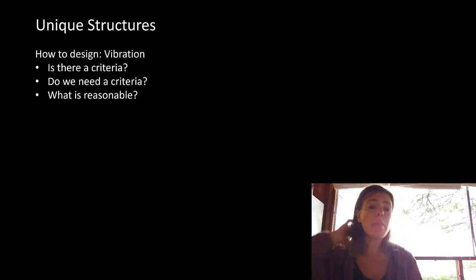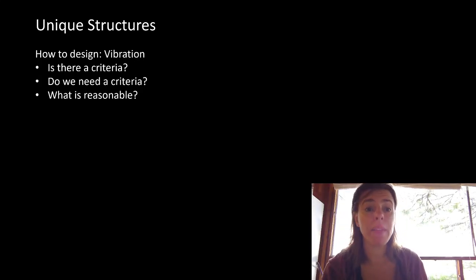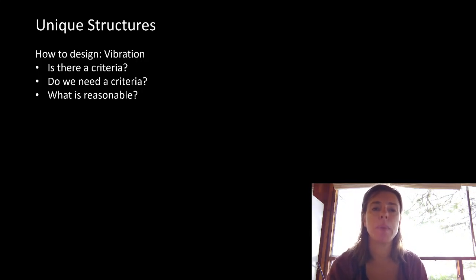Vibration, same criteria or same outline thought process. Is there a criteria? Do we need a criteria, and what's reasonable? Buildings all have vibration criteria, but they rarely are the governing factor. There are things that we're going to talk about where vibration is the number one governing factor in design of these structures. Stairs. Stairs is almost always about vibration. And it's about vibration for a few different things.